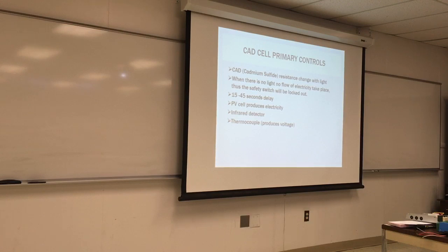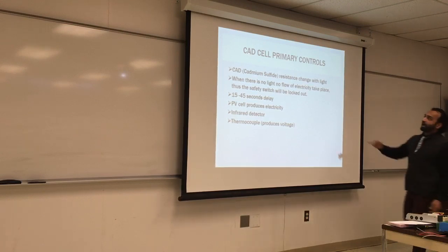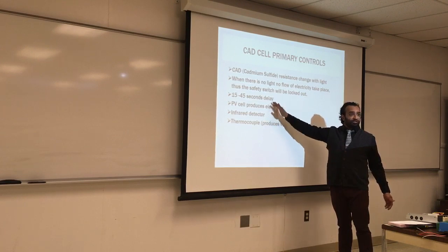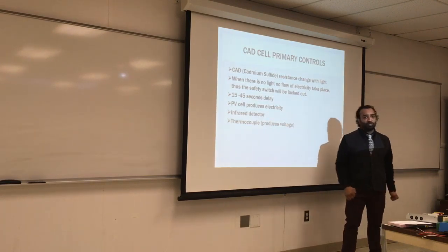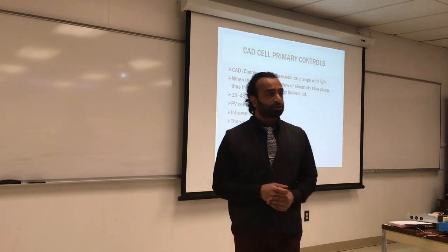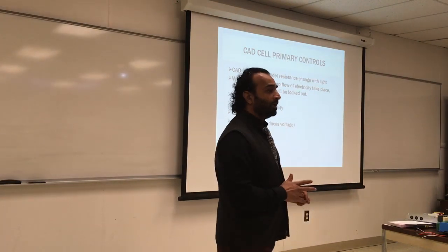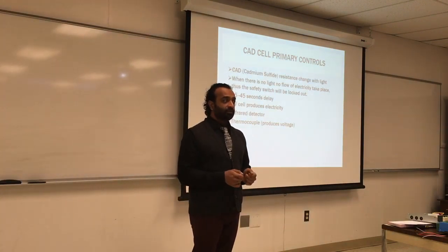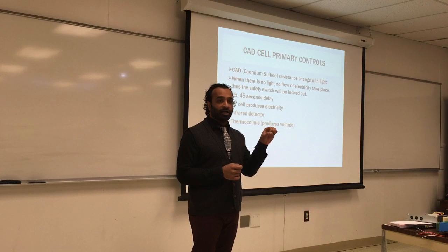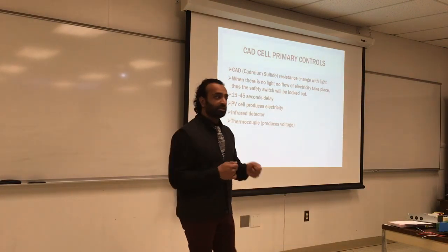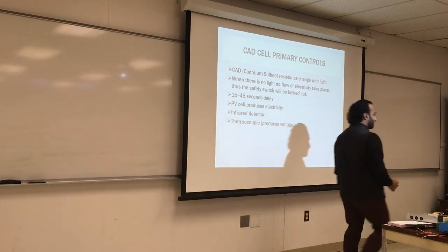Questions so far? If you can just remember the cadmium for now, these we're going to cover in a lot of detail in commercial. For now, in a house or residential boiler, we're only going to use CAD cell. That's the official one. And we learned in the lab how to test this CAD cell, and you see how sometimes by looking at it, you can see if it's broken, if it's burnt, and you can test the resistance and see if it functions properly or not.